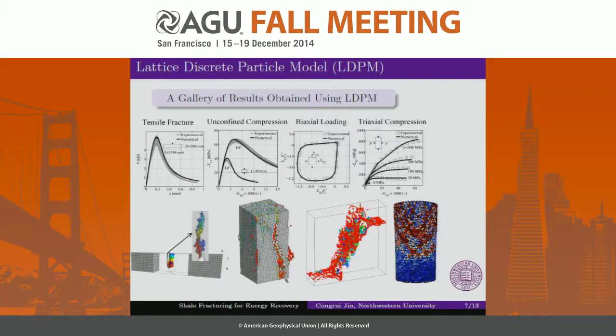For concrete, a mesoscale constitutive law has been established for the interaction between adjacent particles, simulating various features of mesoscale response, including cohesive fracturing, strain softening in tension, strain hardening in compression, material compaction due to pore collapse, frictional slip, and rate effects.